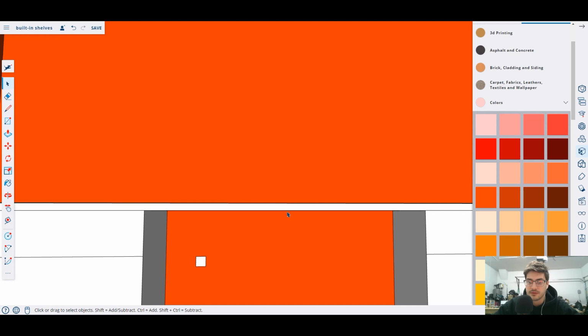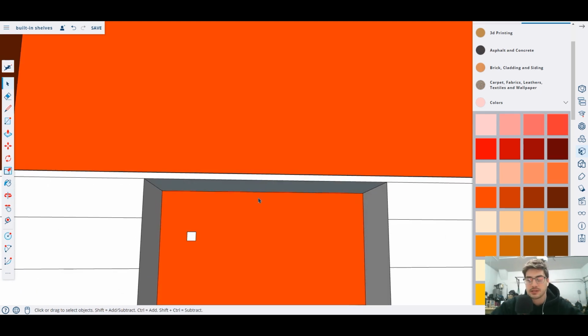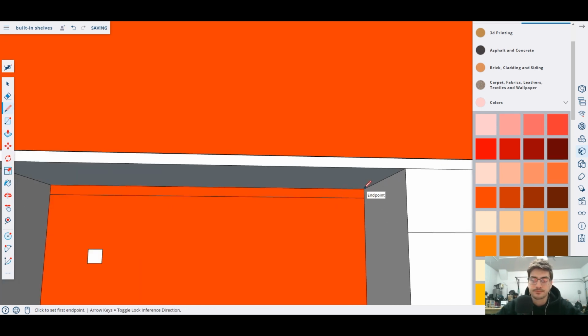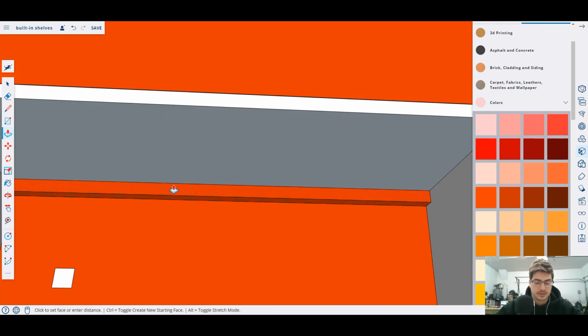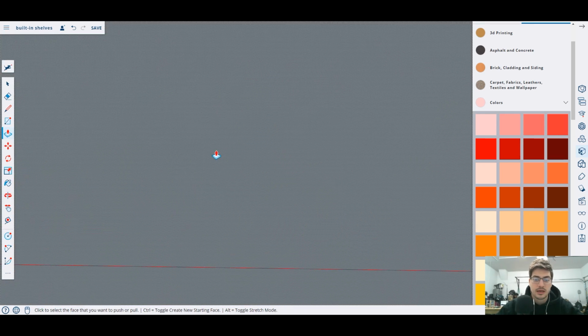And just to remind myself, I need to have some bracing under here. This is a long span to go. And if you have 1.5 inches of plywood, it's probably okay. But typically with something this big, what I would do is I would add half of a 2x4. So that's 3.5 inches cut in half. That'd be like 1.75 inches down. And then I would just screw that into the wall. And then it would come out like 1.5 inches, maybe more than that. Let's do 3 inches. Okay.